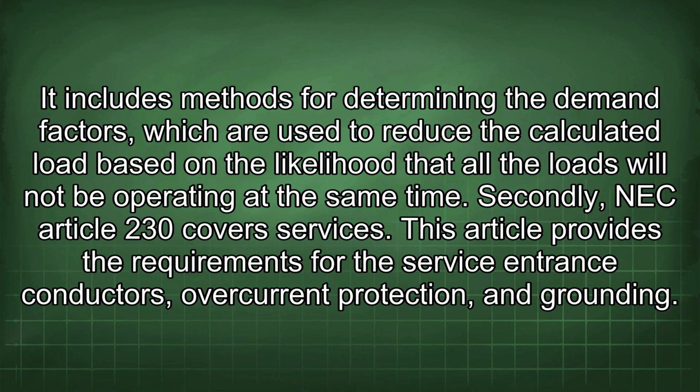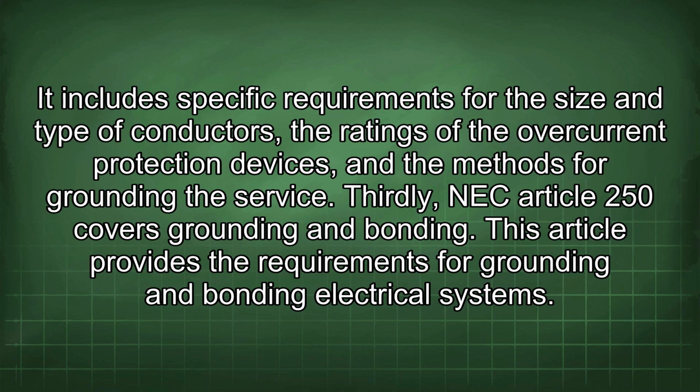Secondly, NEC Article 230 covers services. This article provides the requirements for the service entrance conductors, overcurrent protection, and grounding. It includes specific requirements for the size and type of conductors, the ratings of the overcurrent protection devices, and the methods for grounding the service.